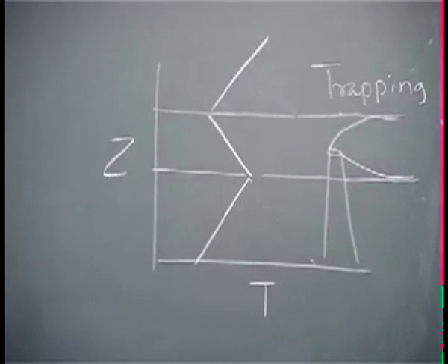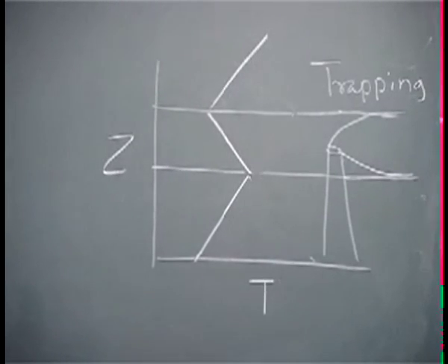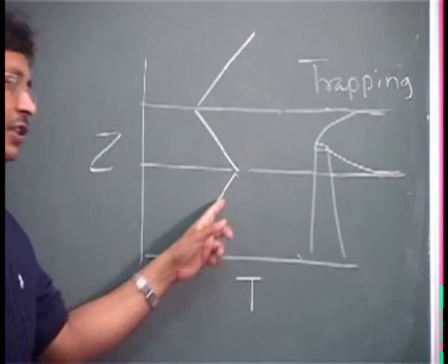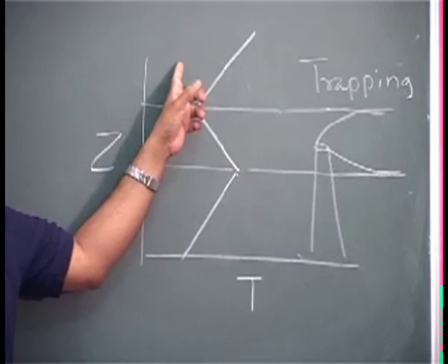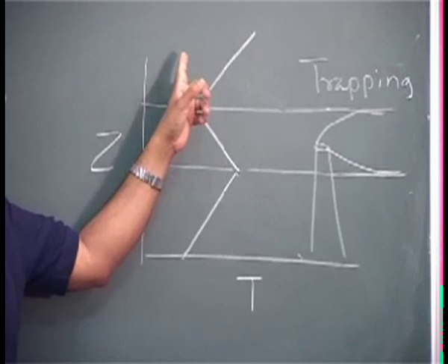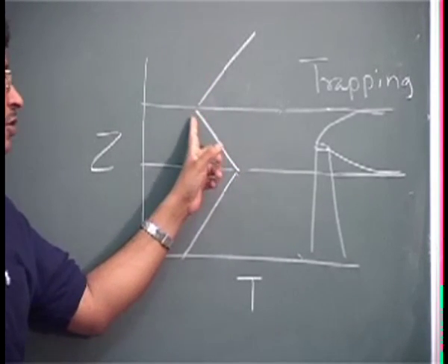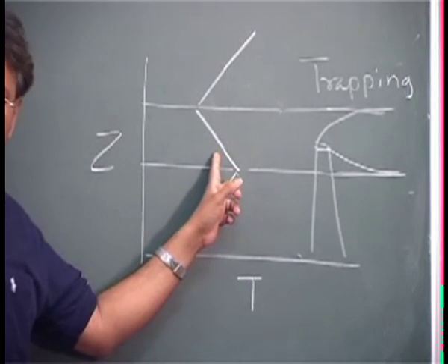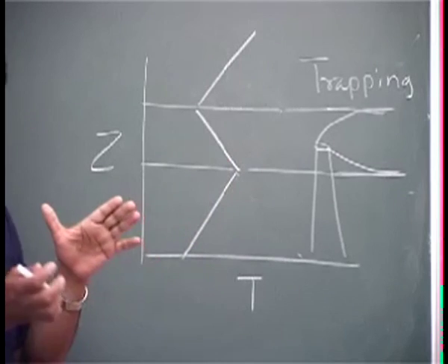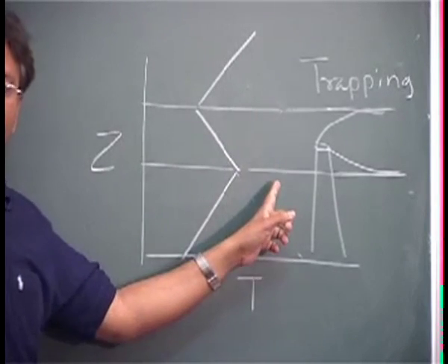I was just scanning somebody's notes. So you see here, since this is inversion, no dispersion can take place here. There is again elevated inversion, so there is no dispersion that can take place here. Okay. Here you see either the conditions are neutral or unstable. So in that little layer which is left, that's where the dispersion will take place.